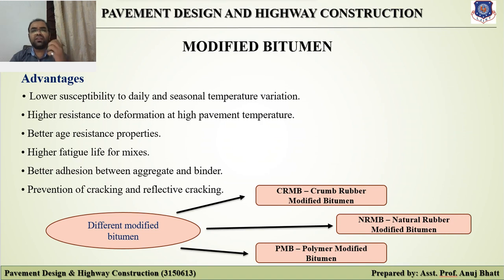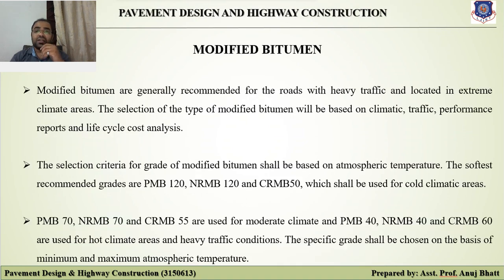So modified bitumens are generally recommended for roads with heavy traffic and located in extreme climate areas. The selection of the type of modified bitumen will be based on the climatic condition, traffic performance reports, and life cycle cost analysis. The selection criteria for grade of modified bitumen shall be based on the atmospheric temperature.